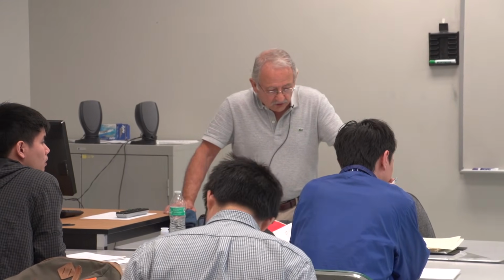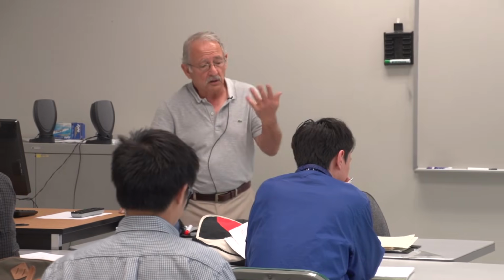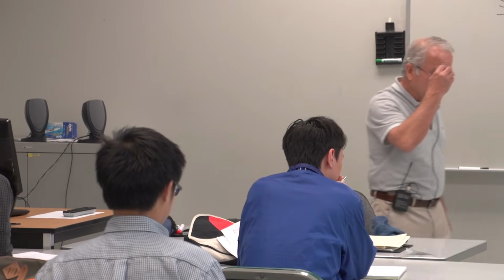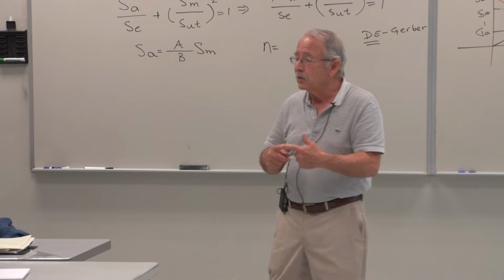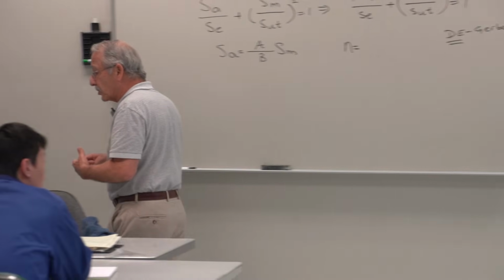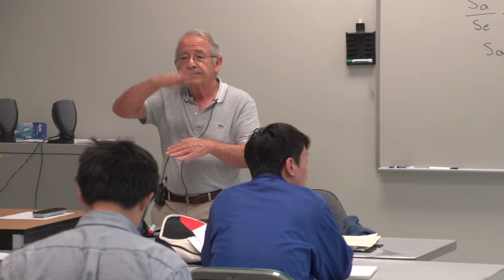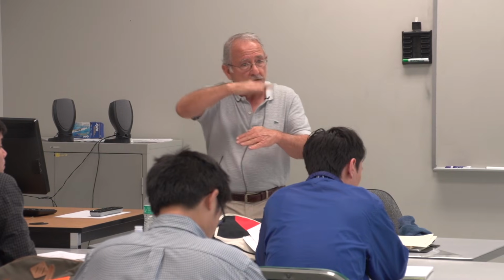But when a shaft carries a load, even when it doesn't carry an externally applied load and it's under its own weight, and it rotates, it will have a tendency, due to the speed of the rotation, to deflect. And that deflection changes, and it does a type of vibration called whirling. In whirling, the deflection of the shaft keeps increasing to a point where the shaft fails, basically breaks. We would like to avoid that.